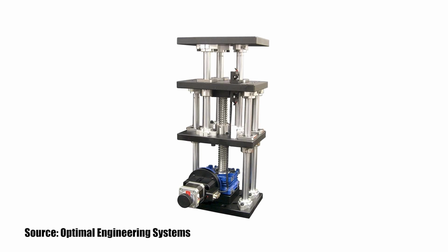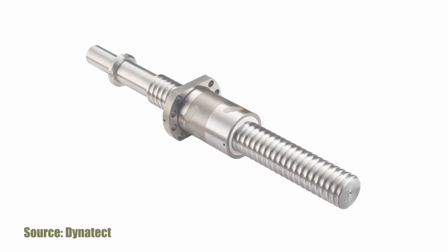Even though our calculations indicate that the ball screw is unlikely to backdrive, safety is always the most important consideration in a vertical application. Knowing the probability that a load will cause a screw assembly to backdrive is not a get-out-of-jail-free card to disregard fail-safe mechanisms. Instead, this information should be used as a tool to help you choose the appropriate safety mechanism, such as a supplementary brake or a counterweight, to prevent equipment damage or personal injury.